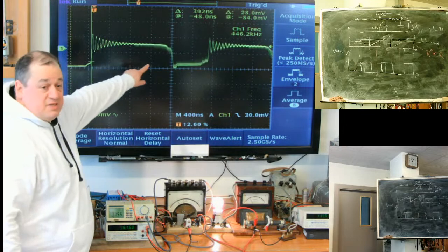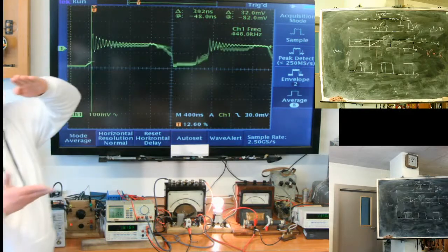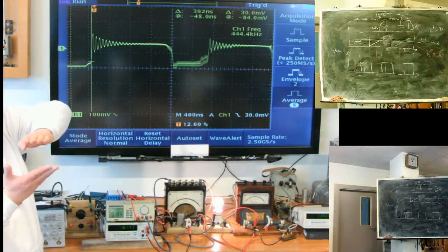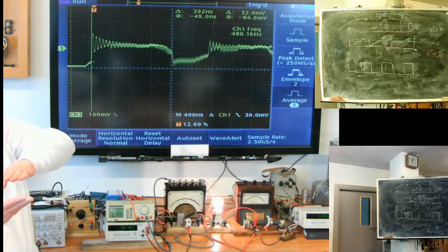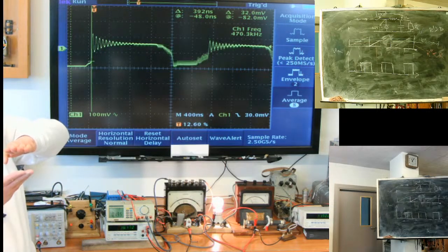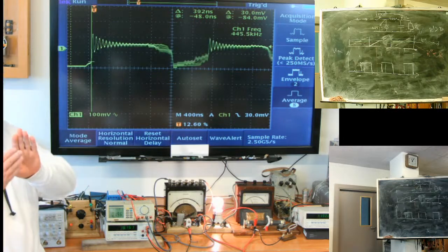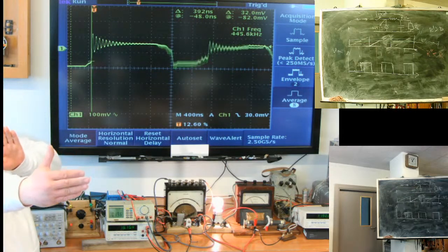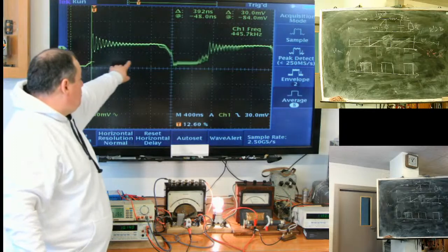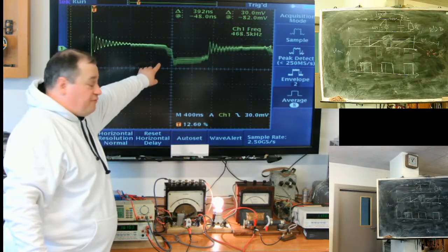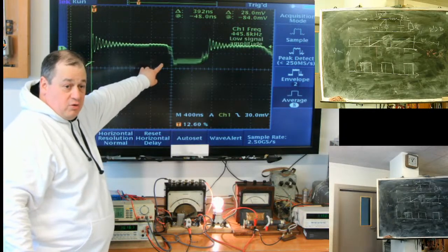You see what happens with the pulse? The supply voltage decreases, the amount of energy the load will receive also decreases. What did the controller do? It elongated the pulse. The PWM controller keeps the amount of energy supplied to the load constant.